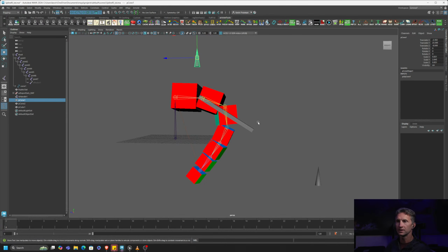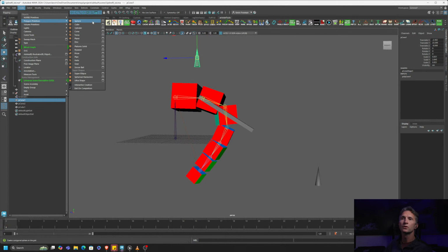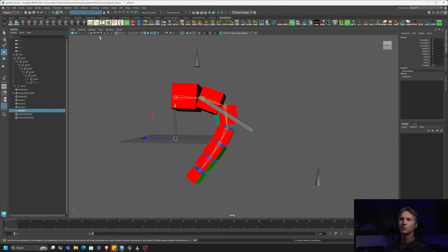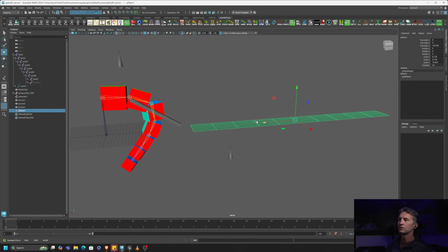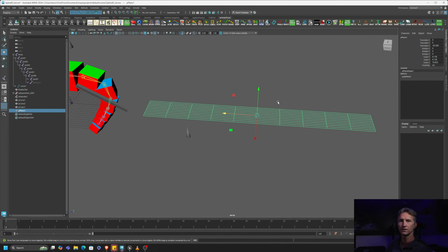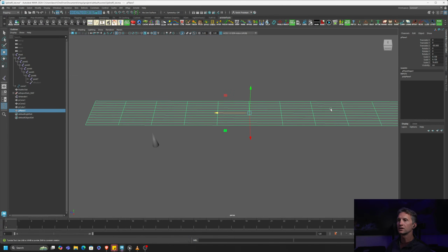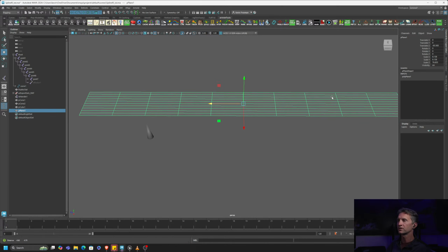That's to prevent popping. Now, let's talk about one other thing that I think is at least worth calling out before we move into Unreal. One of the things that people do to combat this problem of stabilization and not knowing which way is up is they'll get super fancy. Rather than using a spline, they'll use a spline combined with a surface, and they'll create a spline that runs down the length of the surface.